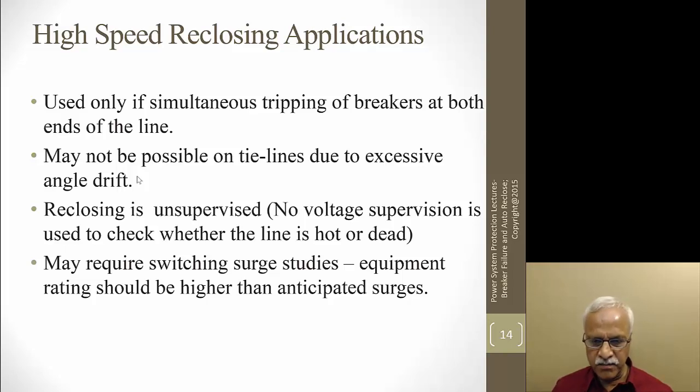And then, as I mentioned here, we might need switching surge studies. Equipment rating should be higher than the anticipated surges when you try to reclose for a permanent fault. That is more important for us to look at.